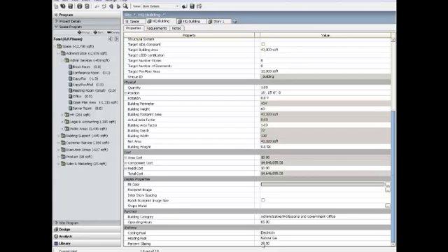If we scroll down to the bottom, you can see some of the properties that we input in the questionnaire, like percent glazing. So as I mentioned before, we can change these at any time to improve upon initial analyses. For instance, in the last section, we learned that winter is a predominant season in this location. In this case, we might want to decrease the percent glazing to allow in more light and heat into the building. And here we can change that to 25%.